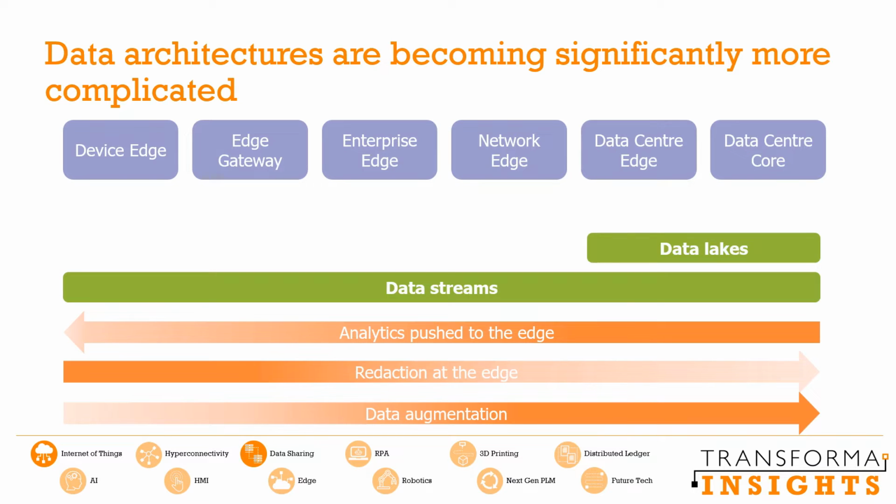Lastly, information flowing from edge devices can be augmented as it flows across the various edge assets by associating contextual and other information, often including information from other local devices. For instance, in a machine monitoring example, as just described, the machine may have onboard sensors to monitor operating temperatures, and computers located at the device edge or edge gateway level could be well placed to identify increasing device temperature if that's the result of some kind of malfunction. However, relevant contextual information might be that factory air conditioning systems have failed, and thus it's likely that increasing device temperatures are simply a product of reduced cooling input.